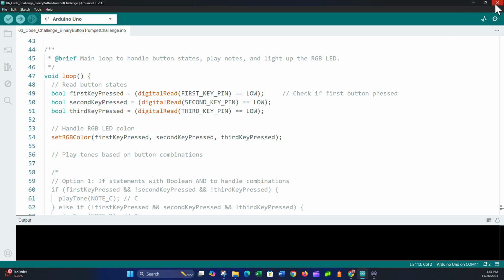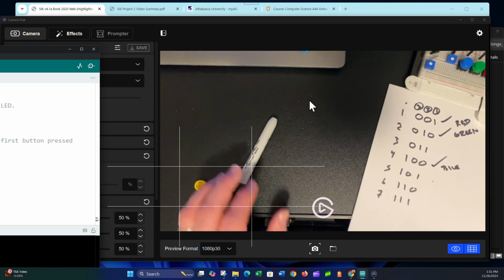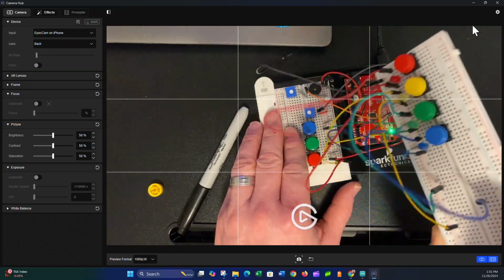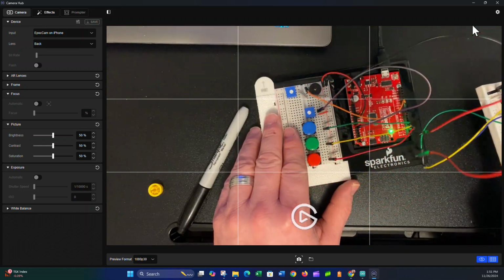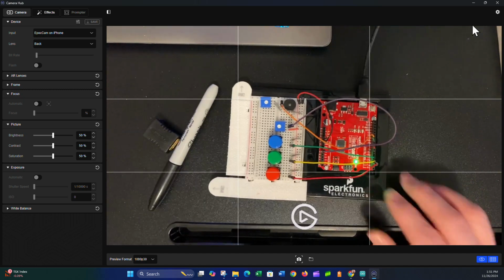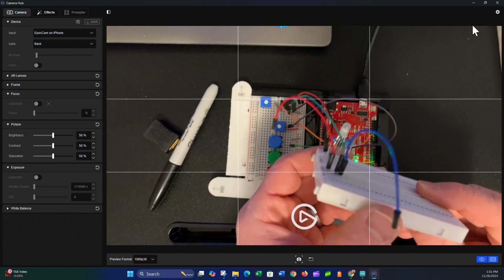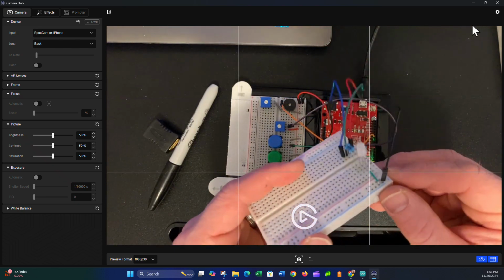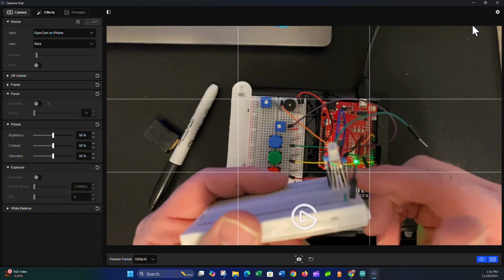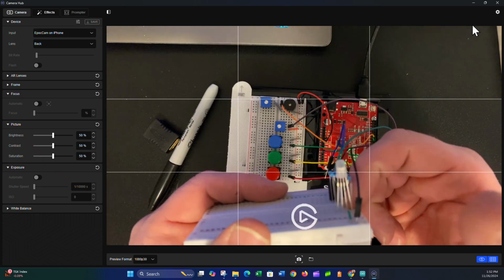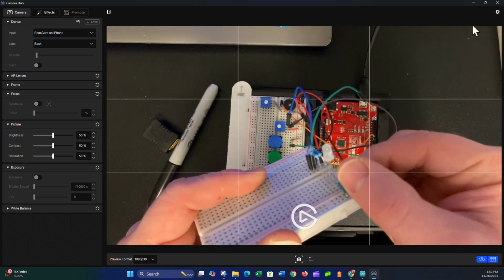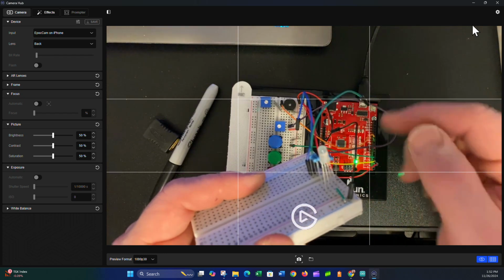So I'm going to show you, we're going to have to hook this up though quickly. I unhooked this mess that, if you were watching the previous videos, was attached to the board. That's for the final circuit, the Simon Says project. But for this one, I've created the RGB LED on a separate breadboard here, and you can see, hopefully, there's 4 pins on the RGB LED. The second pin in, which happens to be the longest pin, is attached to ground, with this ground rail, which I've got a black wire hooked up that will hook to the ground on the microcontroller.